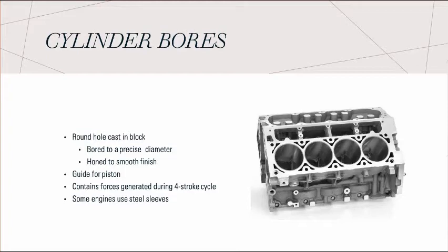A piston is seated inside each cylinder by several metal piston rings, which also provide a seal for compression and the lubricating oil. The inner surface of the cylinder is formed from either a thin metallic liner, which is also called a sleeve, or a surface coating applied to the engine block.